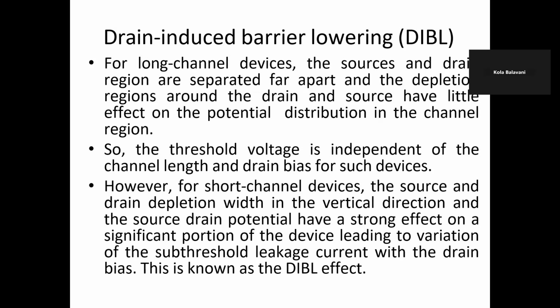First, drain induced barrier lowering. If you consider long channel devices, the source and drain regions are separated far apart, and the depletion regions around the drain and source have little effect on the potential distribution in the channel region.